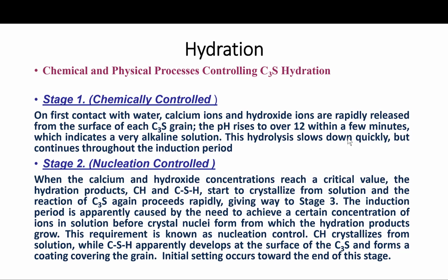So in other words, as has been suggested in some of the text and the literature, in pure C3S the induction period may be the length of time it takes for calcium silicate hydrate to begin nucleation, which may be linked to the amount of time required for calcium ions to become supersaturated in the solution. So that's one other explanation for the dormant period.